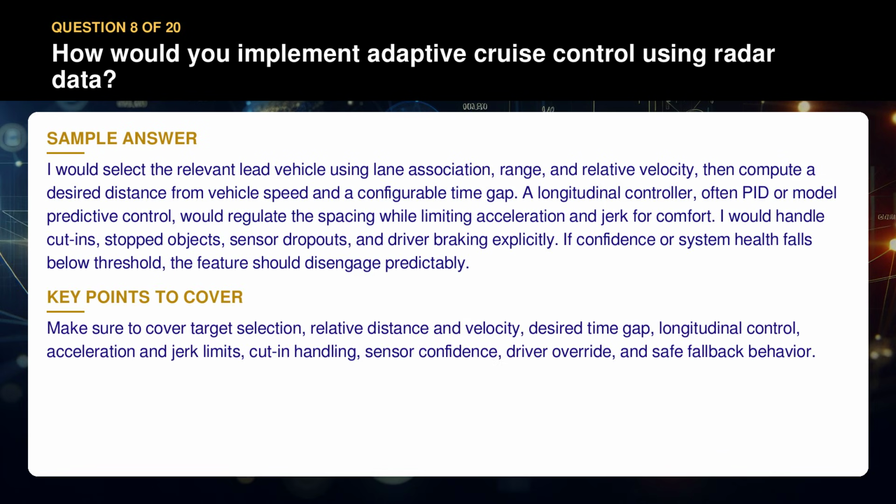Make sure to cover target selection, relative distance and velocity, desired time gap, longitudinal control, acceleration and jerk limits, cut-in handling, sensor confidence, driver override, and safe fallback behavior.